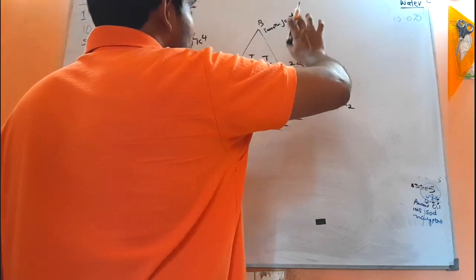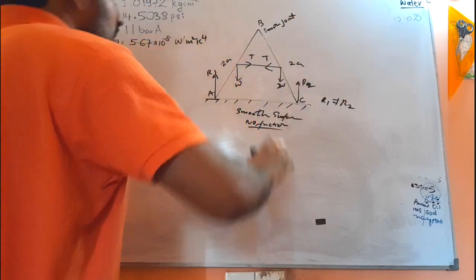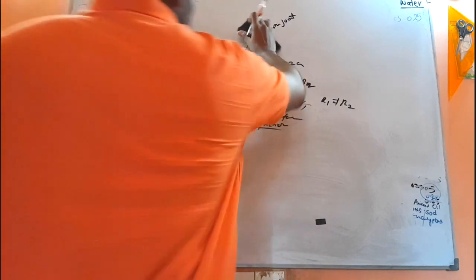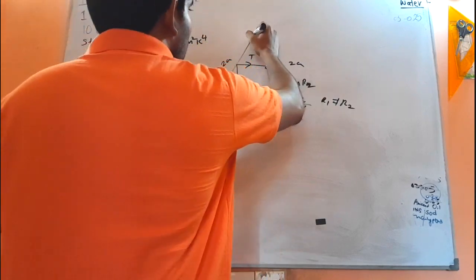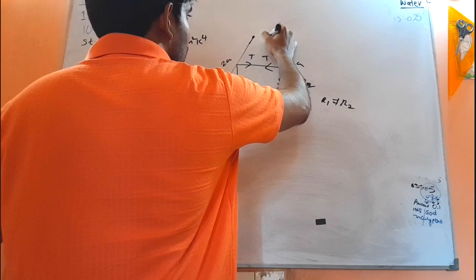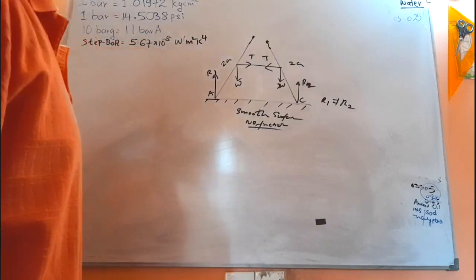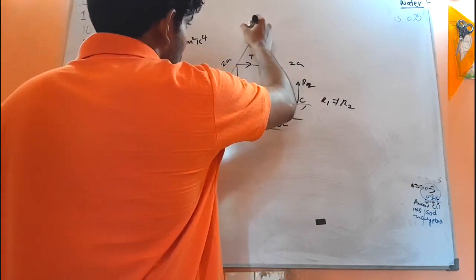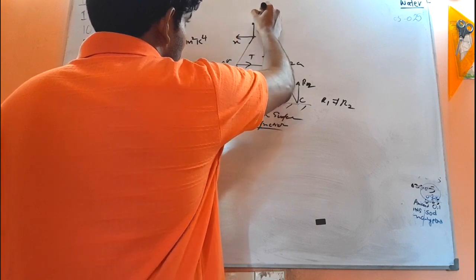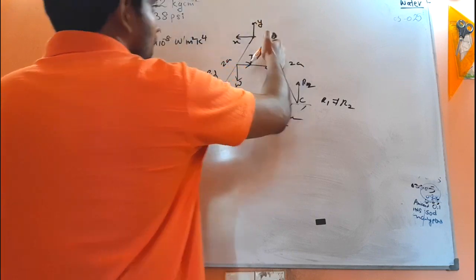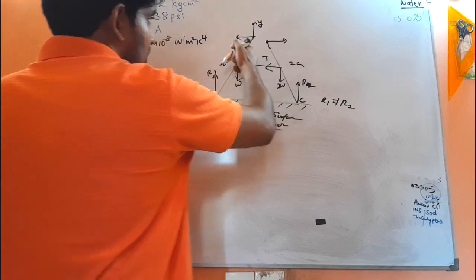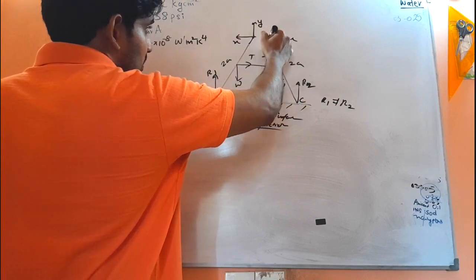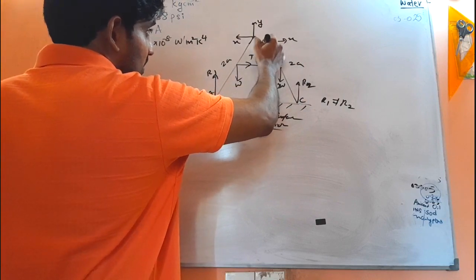Now this joint I am going to break, like this. This is one end and this is the other end. Now I have damaged the joint, so I am going to mark the reaction force on this end as X and this as Y. On the other end, the horizontal force X and this Y will be in the opposite direction, like that.